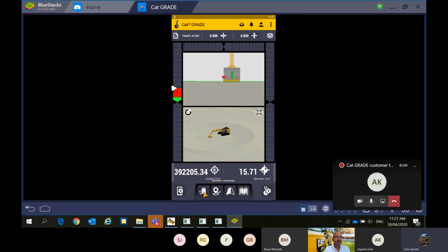So again, when you're checking to make sure that you're getting the right point, make sure you've got the focus point selected on the right side of the bucket that you're actually putting on the control point. Fantastic. So it's fair to say that if you're using a tilt hitch, that's where you would need to change that focus point, right? Yeah, and that's a good way to check the bucket accuracy on a tilt hitch. We'd put it on the left-hand side, swap across to the right-hand side, and double check both sides. That's going to make sure that it is accurate.